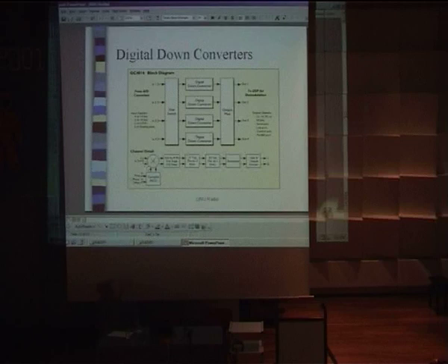So the trick is, by steering this NCO, I can effectively tune, because this is just a numerically controlled oscillator. I multiply the signal coming in by this, and then by basically twisting this knob, I select which one I want, and then I filter out all the aboves and belows, and I get what I want. And then they decimate from here, and this resampler is for interpolation. It allows me to basically get a lot of pictures and all.